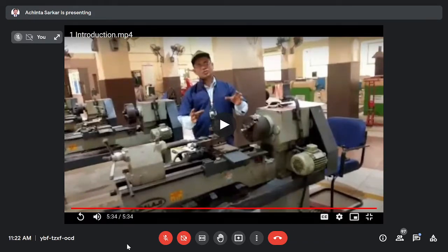So you can see where the chuck is mounted. That part is called the headstock. The headstock has one gearbox, and that gearbox is called the speed gearbox. The speed gearbox is connected directly with the motor. You know that the motor provides mechanical power, converting electrical energy to mechanical power, and through belt and pulleys, the motor and your speed gearbox are connected with each other. So power will be transferred to your speed gearbox.